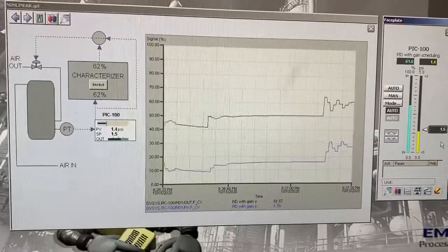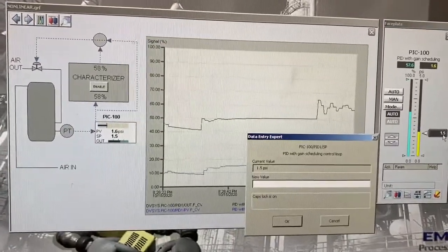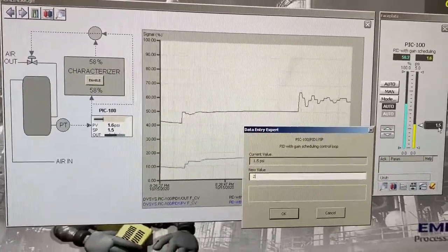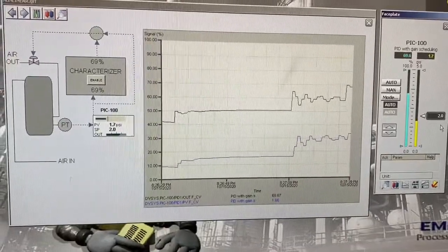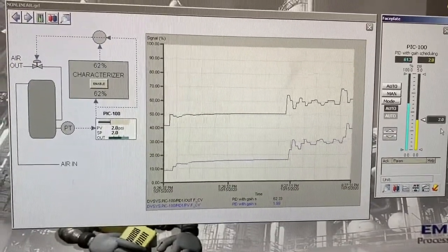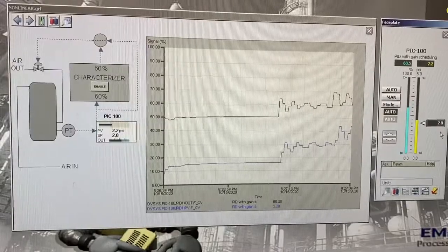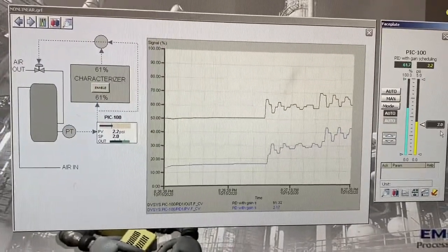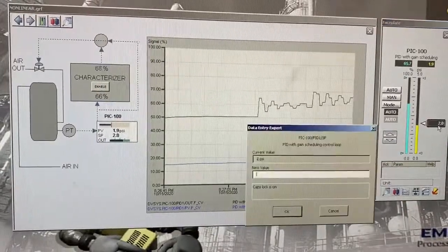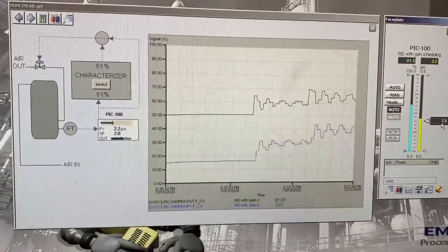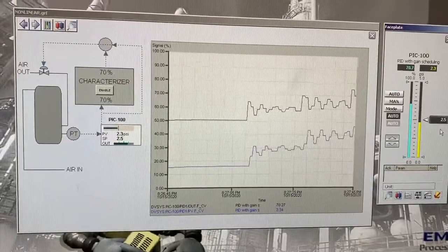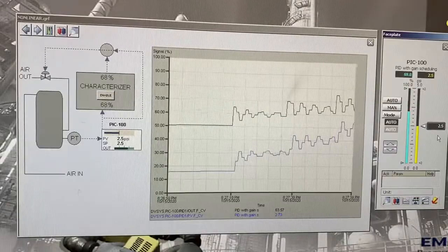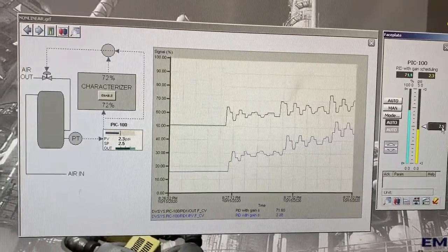So yeah, it's definitely oscillating more here. And let's step this again. We'll go to 2. Oops, not 20. We want to go to 2. So it doesn't look very stable now because you can see it's in sustained oscillation here. Let's go to 2.5. Definitely in sustained oscillation.